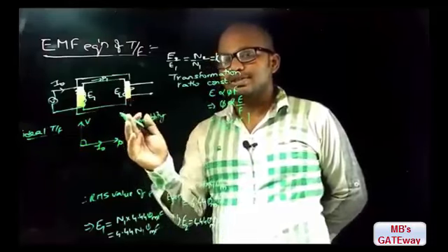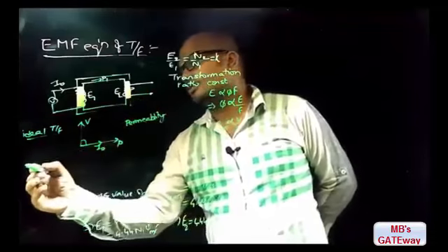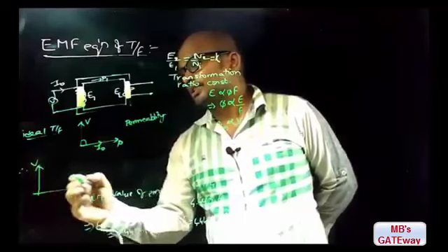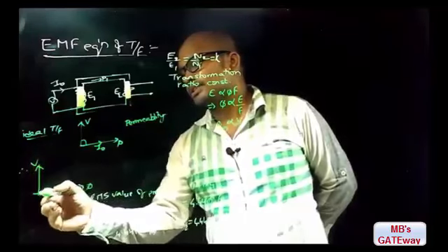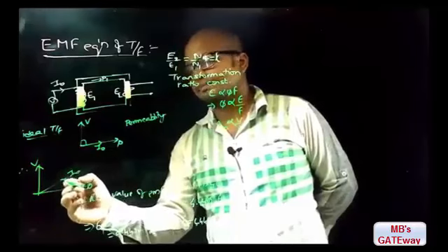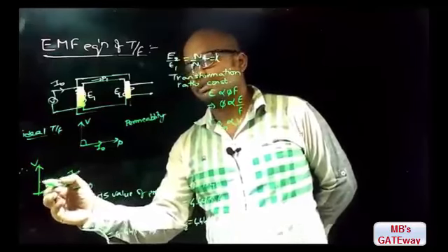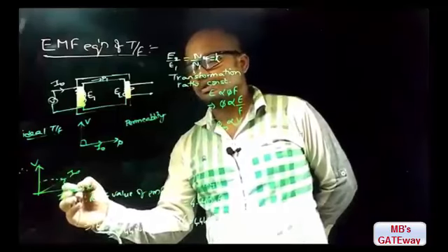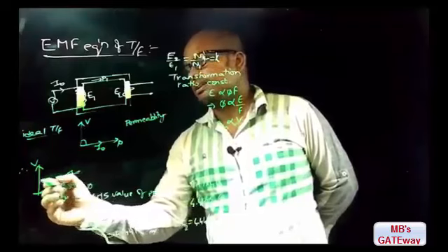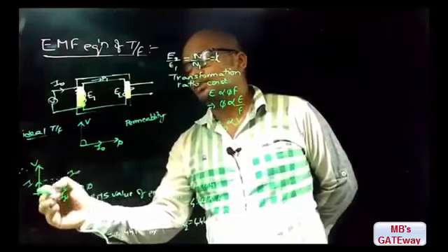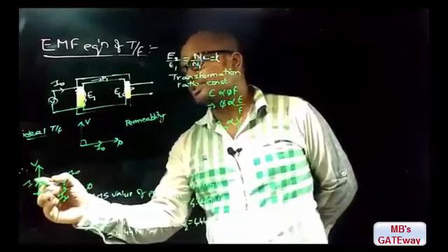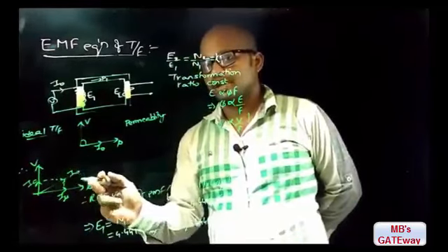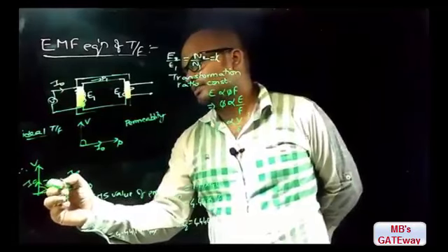But with excitation, permeability will change. Therefore, in case of a normal transformer, V and flux will be like this and I naught will be like this. Therefore, I naught will have two components, one along the flux, which is called the magnetizing component of no load current, and the other current which is drawn along the input voltage is called Ic, which is the core loss component of no load current, and let the initial power factor angle be phi naught.